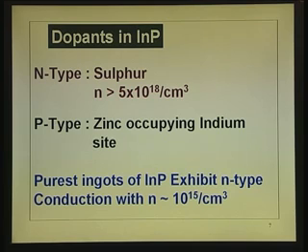Let us not ignore indium phosphide all the time. Let us give it a chance also here. You see, dopants in indium phosphide, yesterday itself I mentioned, they just reproduced the thing on that. That is, you can make it n type, not compensation, by intentionally doping with sulfur, or intentionally doping with silicon. You can make p type with zinc.